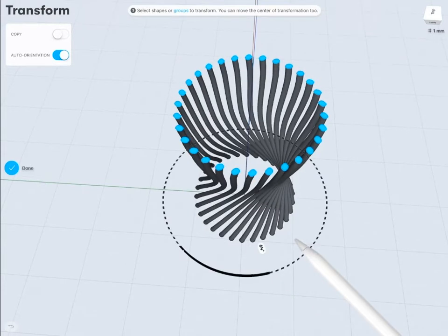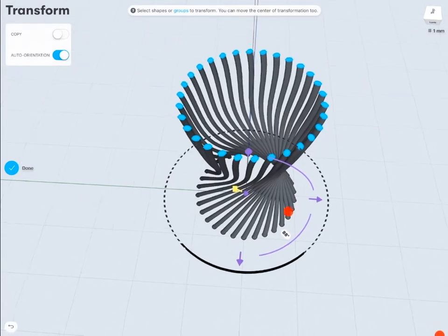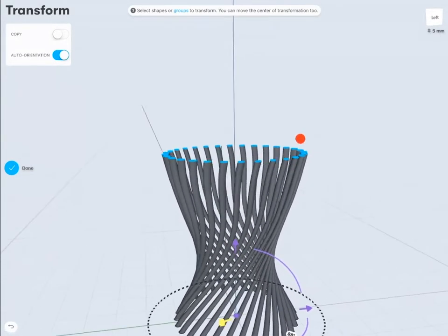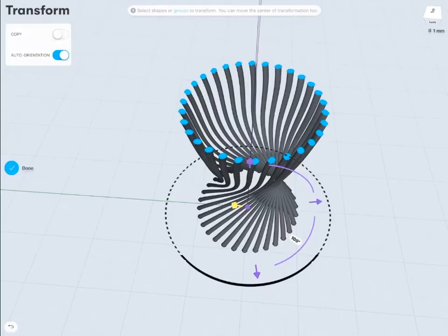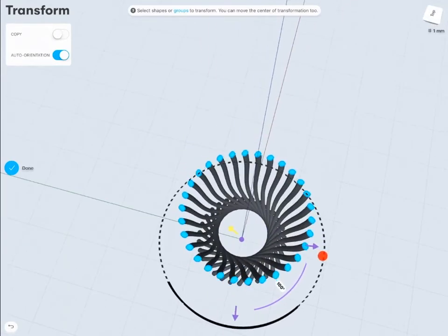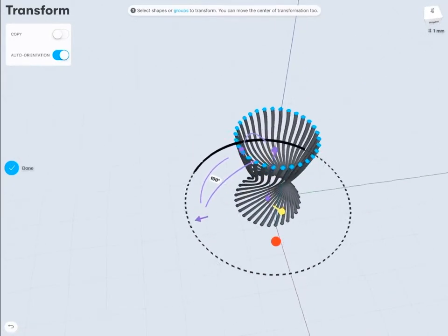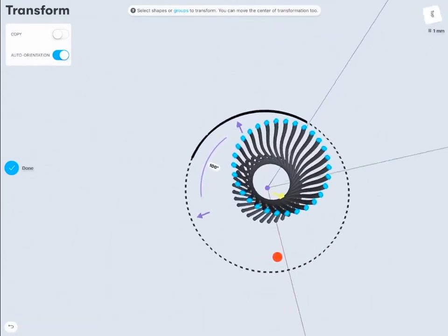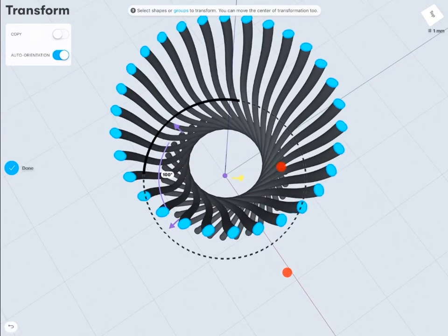Now, I'm going to use one of the arcs of the coordinate transformation tool to rotate the top cups. Once you rotate them, all selected faces are rotating, and all the bodies are transformed into that position. So this is a really great tool because it gives you the ability to transform your designs in an organic way. You can also modify all the bodies you've created on your stage by just dragging the edge or the surface and just transforming by scaling or rotating.